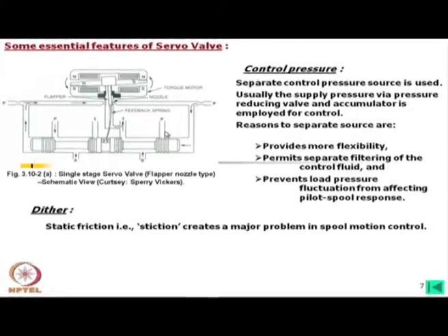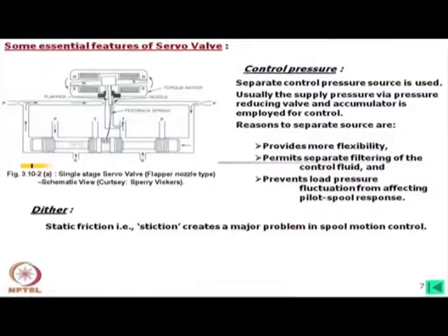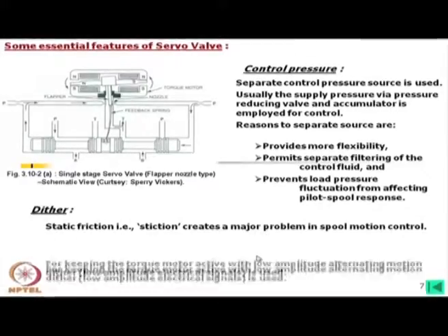The outside stiction we do not have any control of in this valve. We can expect a smooth system, but there may be higher stiction at the application end also. However, what we are talking about is the stiction of the spool inside this valve, and that creates a major problem.